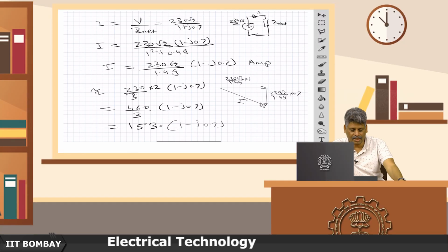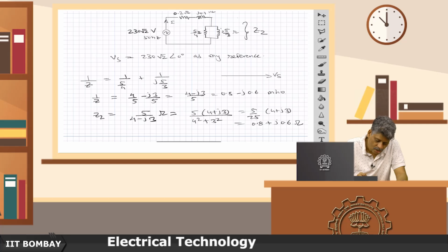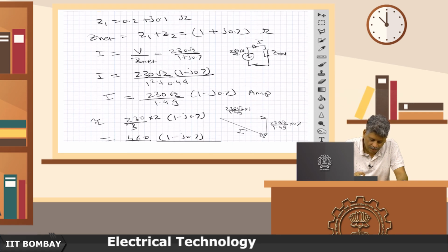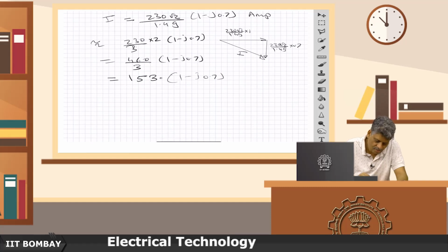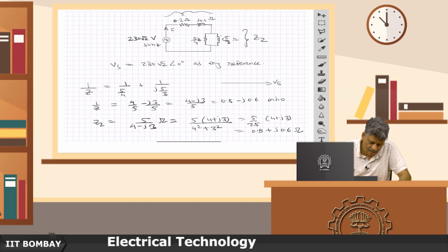So, this is actually a large current. Actually, these impedances will be at least 10 to 100 times this particular value. They will not be so small. I knew it when I took it itself, that they will be much larger than this, and this much, 153 amperes, none of your fuse is going to hold. If you look at your fuse, you have 5 ampere, 10 ampere, 15 ampere, that is the kind of rating of the currents that you see in your home appliances. 153 which I have got in this numerical example, which I just cooked up on the fly, is way out of